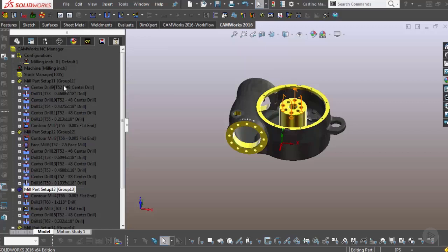In our next lessons, we'll go over a little bit more where we're actually doing edits and we're doing changes and we're telling CamWorks, hey, I want to use this tool, I don't want to use that tool. I would really prefer to do a spiral lead-in versus a standard lead-in, and we'll get a little bit more in depth into this.